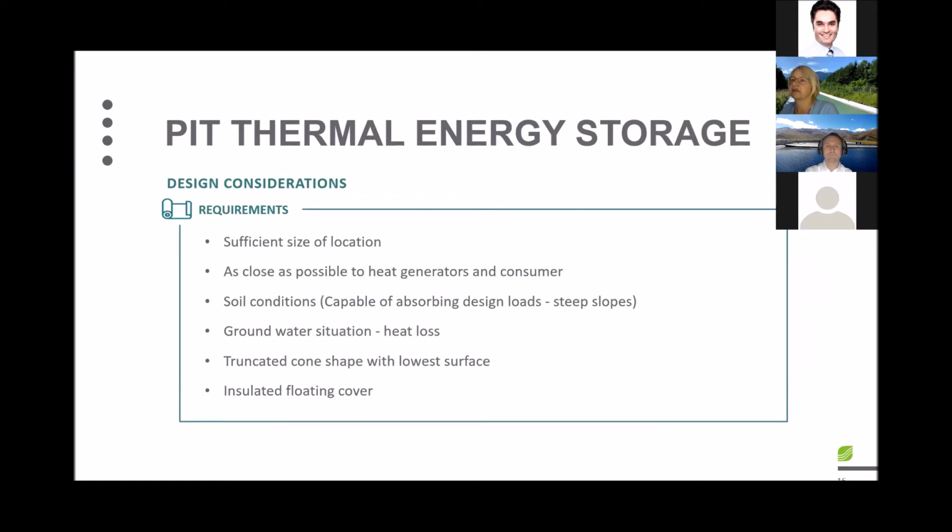What are the necessary design considerations in such an application? We need at first a sufficient size of that location. So it's not a small application anymore, and it needs to be considered with regard to the environment. It shall be as close as possible to the heat generators and to the consumer in order not to lose energy over the transport distance. The soil conditions need to be considered carefully. They need to be capable of absorbing all the design loads, and they should allow the construction of steep slopes. The groundwater situation has to be considered carefully. We don't want to have heat loss because of flowing groundwater here.